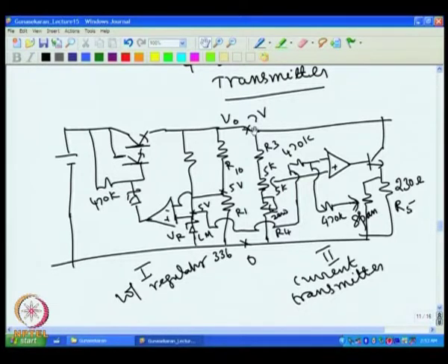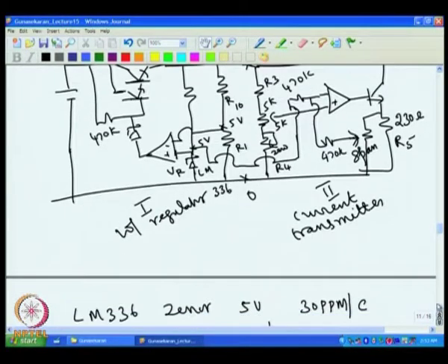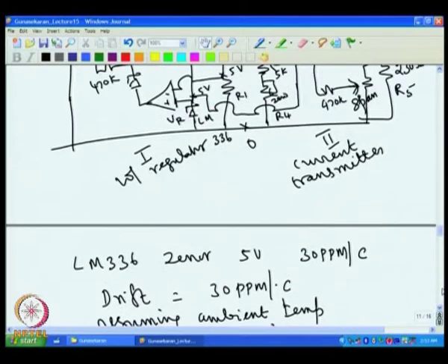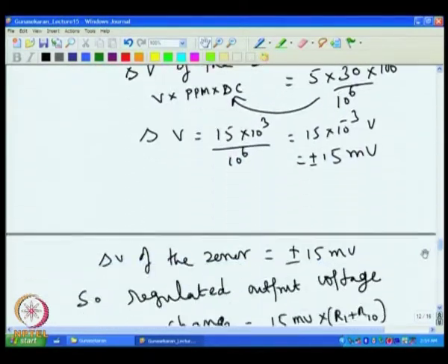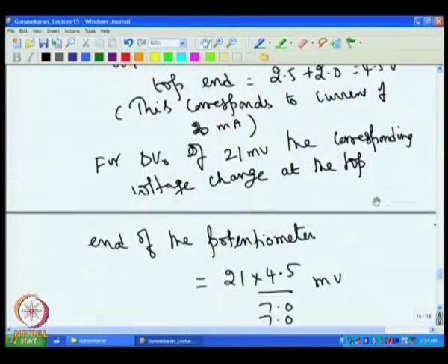We already discussed this. Say, for example, if I use 25 ppm resistors here, one can go up, one can come down, and then we can find out what the drift in the output voltage is. So we have to calculate first R1 and R10, and then we arrive at the expected drift. Assuming R1 as 100K, because we can't keep a low value, that low value will consume a lot of current.